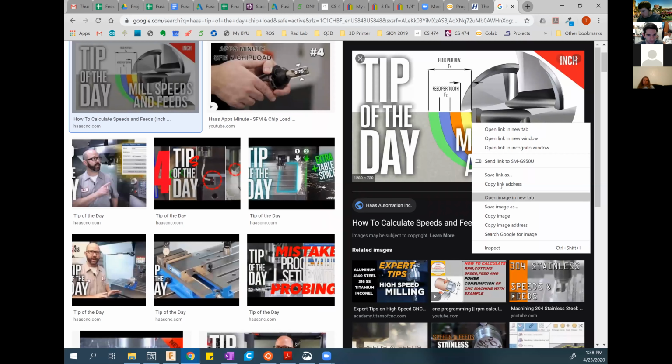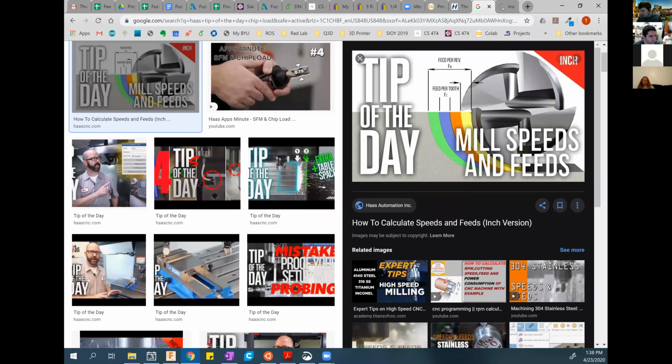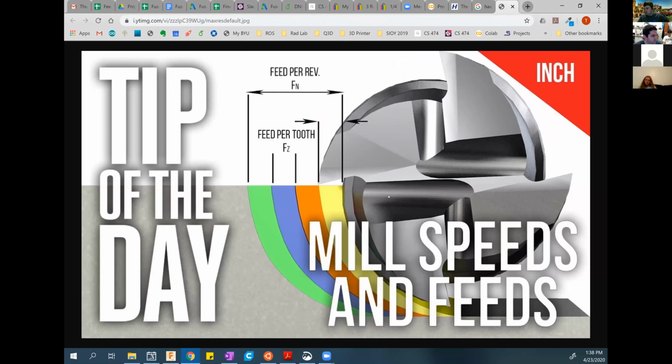So here is an image that helps visualize that. Oh, hello, Tyler. Look at that. Can you guys see this hot tip of the day thing? Mm-hmm. Yes, sir. So you guys are going to watch this afterwards. So this is your feed per tooth. That end mill is moving this direction, and that's the chunk that each tooth bites off of. Another thing that's cool about this picture is it shows it's not a consistently wide wedge, which is an interesting concept. Great. Anyway, thank you, Tyler. Welcome.